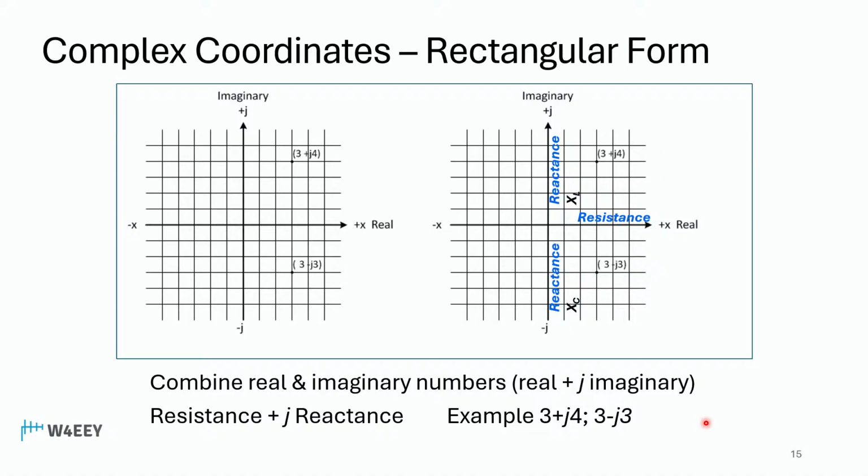So you might be wondering, what happens if the number winds up directly on the x-axis? Well, if that happens, that means it's pure resistance. We don't have any reactance in that impedance whatsoever. Or if the dot winds up on this scale, it's a pure inductor or a pure capacitor, no resistance.